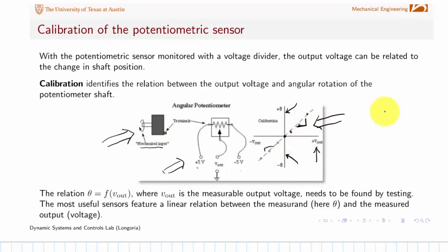By the way, a lot of times you'll make these measurements and you'll find, oh, that guy's not going through zero. The points might have a non-zero value here, and you can get the y-intercept here. A lot of times the reason that happens is, let's say in the case of the pendulum, the shaft might not be centered, and you could loosen that.